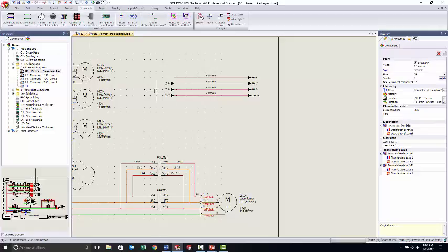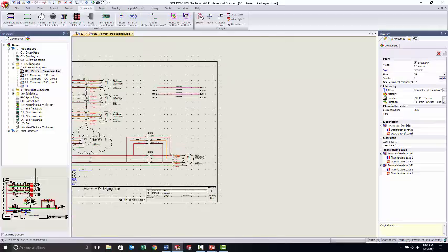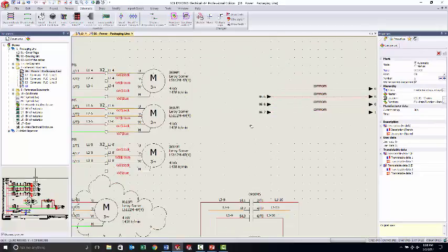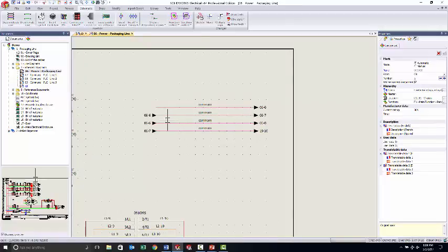So then, like if your grounds were going from sheet to sheet to sheet, that auto connect does work there. That's goofy. Something's goofy. You go from 6 to 6. On my sheet, I've got 3/4 of an inch between here. Oh, okay. So the wires were only at a 1/2 inch, and so there's 2 of them actually.